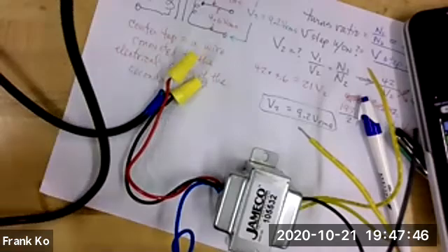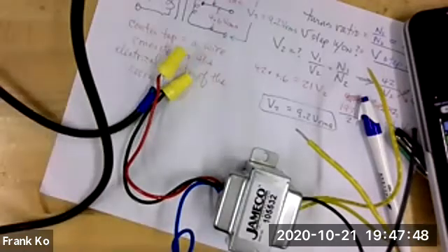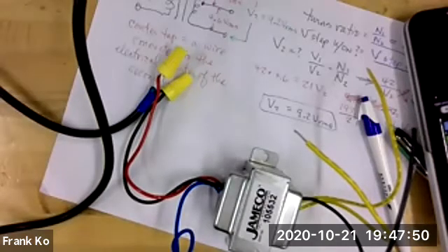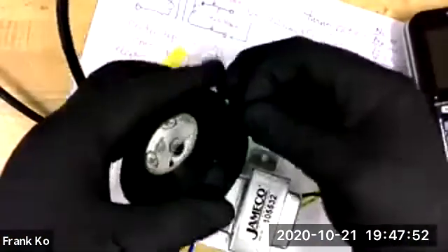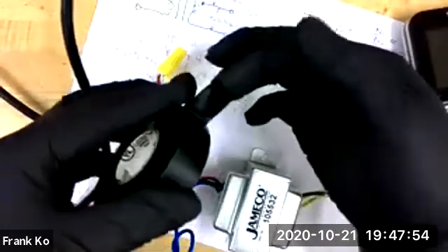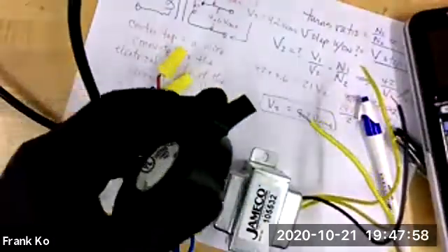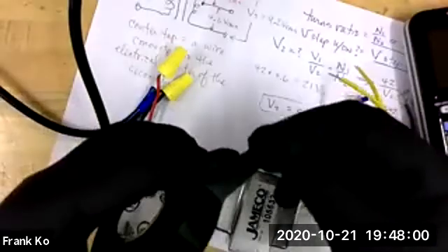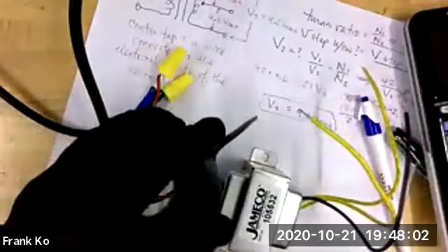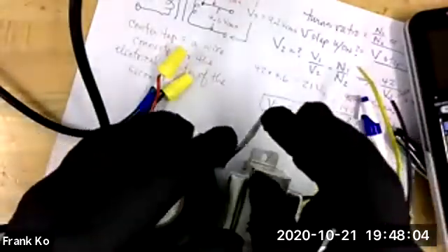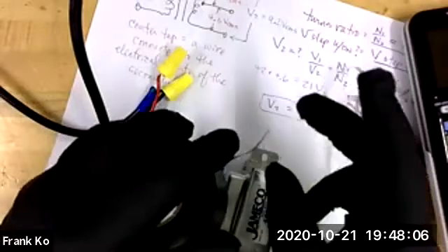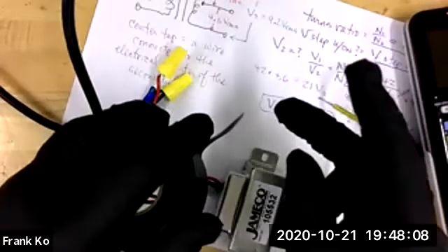Snip it. Now let me give you a tip on what to do when you snip electrical tape. When you snip electrical tape off of a spool like this, it's hard to tell with my black gloves on, I apologize. But what I recommend that you do is you create a tab by folding part of the tape onto itself. My friends, watch this on the screen.